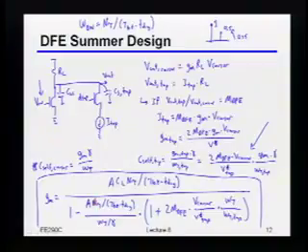Stephen? Yeah. Wasn't the point to substitute the CL with the C self in the numerator? Well, so notice the CL only appears up on the top over here. Right? Because the CL basically is just saying, if I have double the explicit load cap, that never causes a bandwidth limit. It just means that I have to spend twice as much power as I did before to get the same bandwidth. Right? What causes the bandwidth limit is if I upsize my device and I increase my own self-capacitance by that same, let's say, factor of 2, if I'm dominated by driving this, then now I'm screwed. Right? Because I can't independently change my GM from my load cap. Does that make sense? Or?